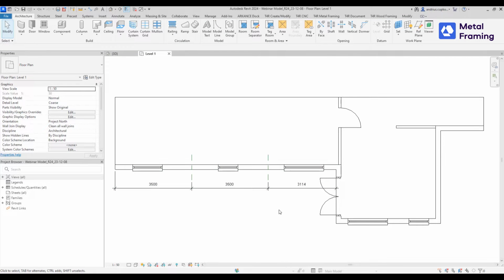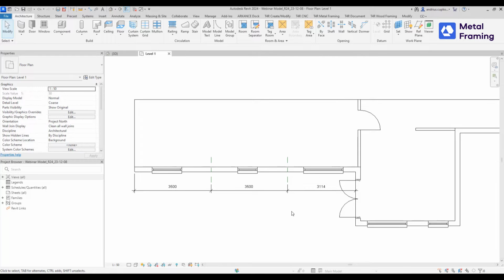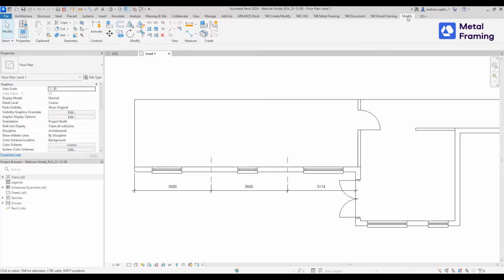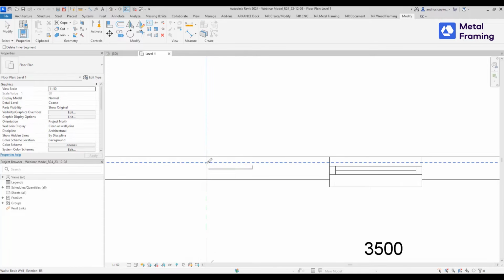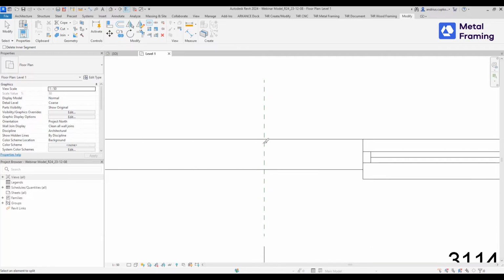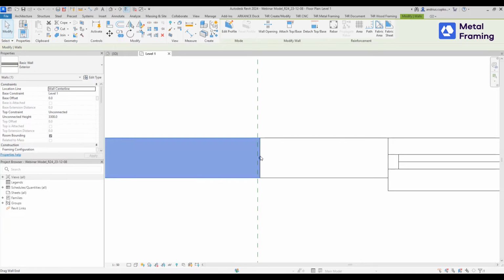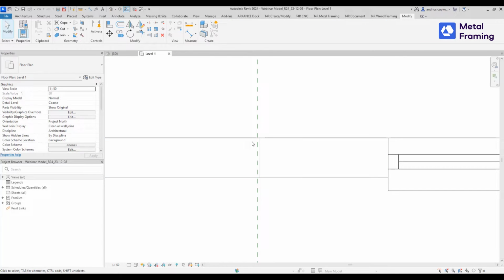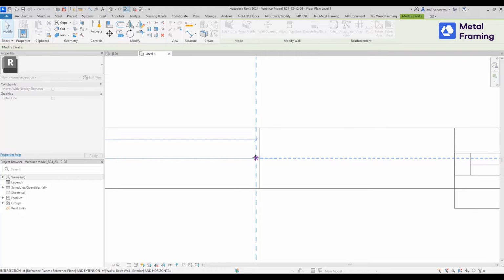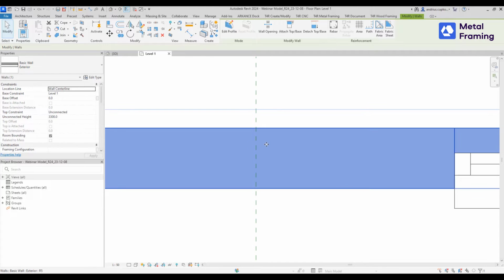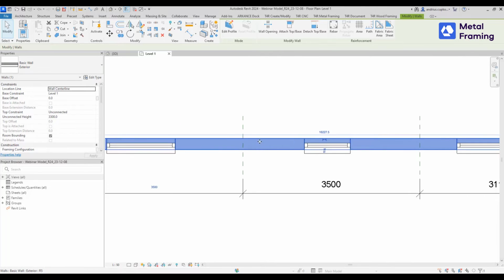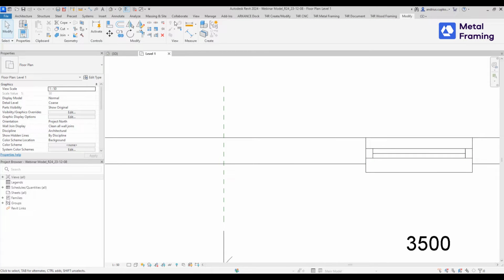Now, this requires a lot of manual effort. And once we have these references set, we can go to the Modify tab in the Revit ribbon and then select the Split Element tool. Now, sometimes it's pretty straightforward, but sometimes it requires some attention to detail because it doesn't always work perfectly. When we try to tweak the ends of the walls, we might accidentally merge these walls, so we have to start everything over. So before drawing walls, just make sure you untick the box, allow join.